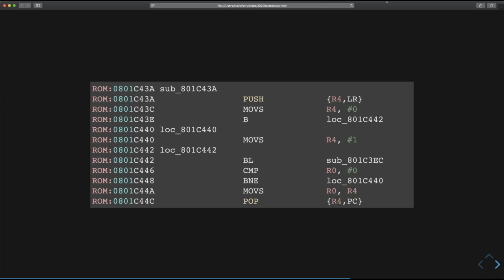This is a neat way to cheaply return, because in popping the value from what was the link register at the time the function entered back into the program counter, it can skip restoring that. We also see a BL instruction in the middle, which calls another function within the program. Jumping there, I find a valid function, which tells me that this is correctly loaded.